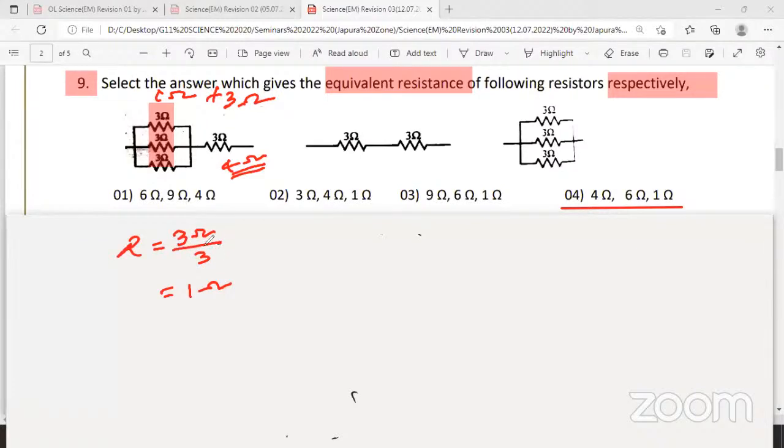What are the two conditions? All the resistances the same value, and they are parallel. Same resistance, parallel. What is the short method? Value of one over the number of resistors. Right. So that's how you get 4 ohms for the first circuit.